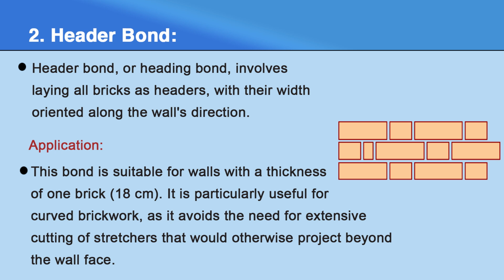Wherever the curved brickwork is to be provided, the header bond is advantageous in such locations, because it avoids the need for extensive cutting of the stretchers.